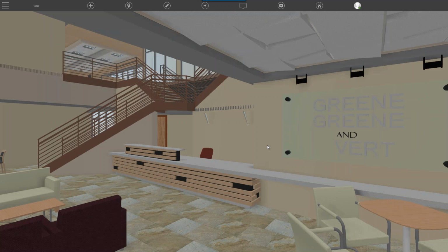light mapping isn't showing up here. So we'll stop this now and switch to the shared model so that we can all see the higher quality model. And then if you're set up to do so, you can also follow along. The camera follow feature is super cool because it'll copy the shared model to your C drive, and when I'm moving the camera through the model, the only information that's being downloaded to your computer basically is the camera position, and you're moving around your own local copy of the same exact model.